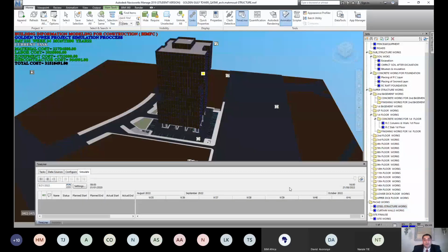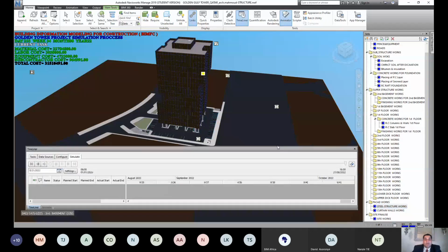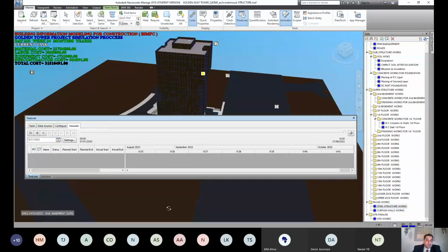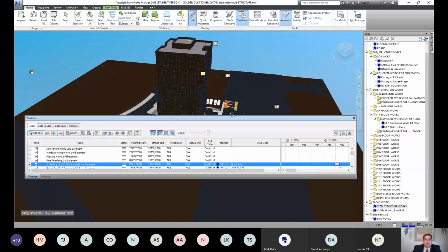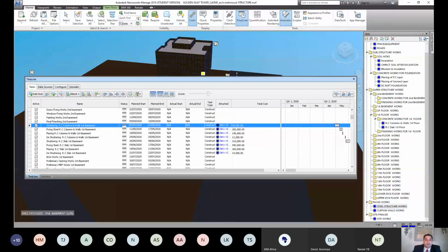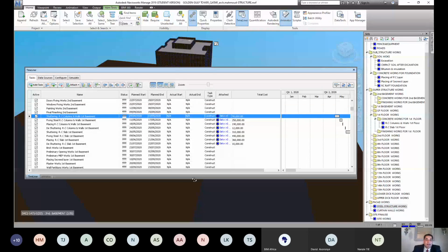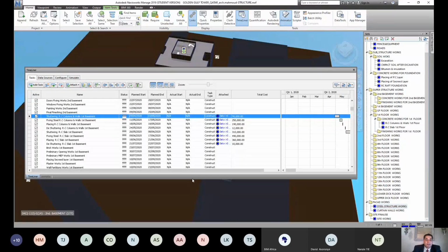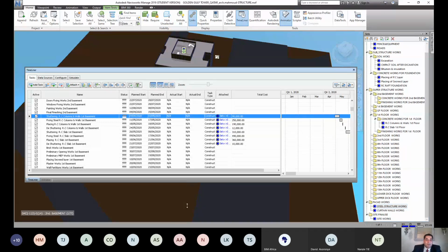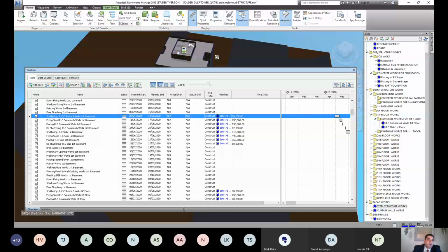Let us start from here, okay? When we make the sheet for the work breakdown structure for the model and the activity in Primavera, we export these items from Primavera and import them in Navisworks like this. Okay, you see it now?